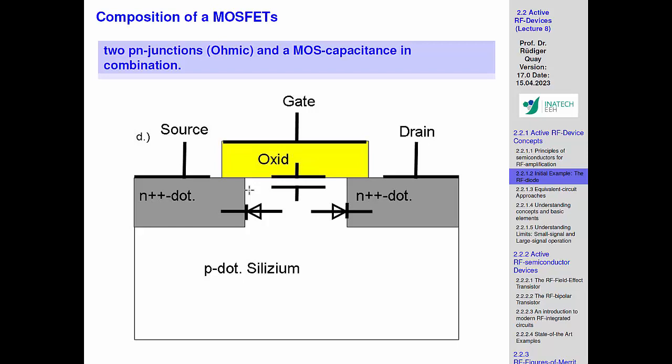And the point I'm trying to make is now this combination of effects. So this generic oxide, or the oxide on top, makes sure that there is carrier formation along this interface. And the trick is now that by the application of two PN diodes, you again create a situation like in the bipolar, where everywhere else you get two anti-parallel diodes.